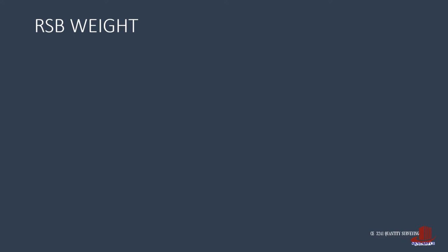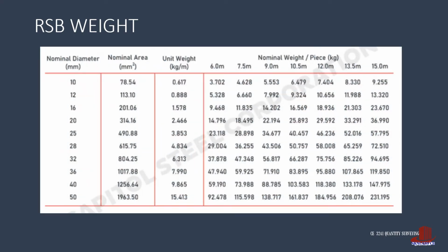Preliminary estimates for steelworks are computed by weight, thus a table is provided to assist us with the weight of reinforcement required. Although computations will be per diameter and we are to find the number of pieces, to avoid a long list of various sizes, estimates are summarized into kilograms so the column of per meter length is provided.